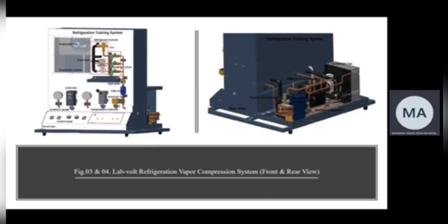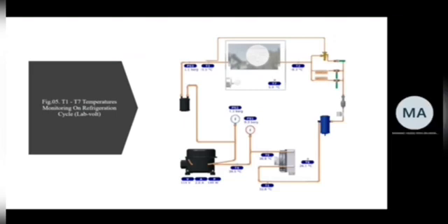The four main components, such as hermetic compressor, mechanical air-cooled condenser, refrigerant control, and air-cooled evaporator, are shown in figures 03 and 04. Then the test points T1 through T7 all provide a proper temperature reading which approximately corresponds to the room temperature. This occurs because the associated temperature transmitters are currently powered via the USB cable between the training system and the computer.